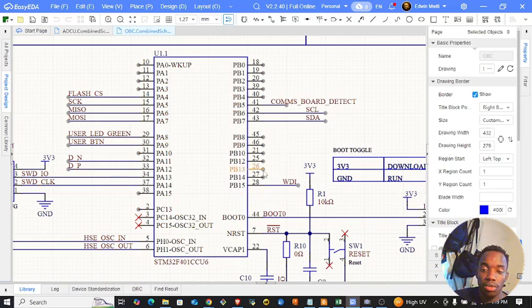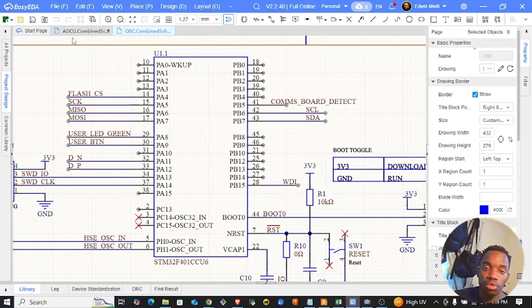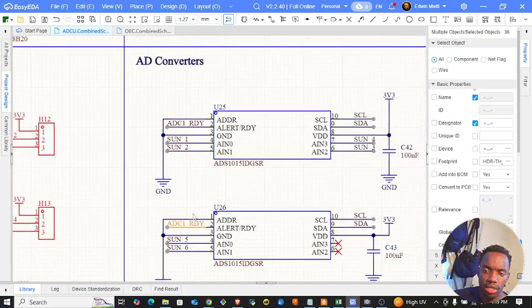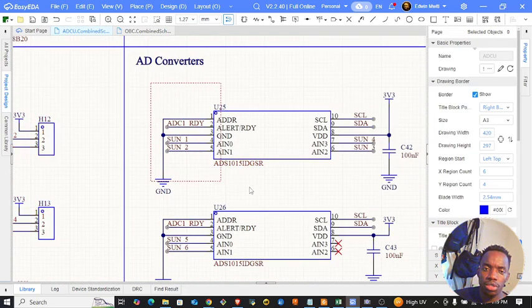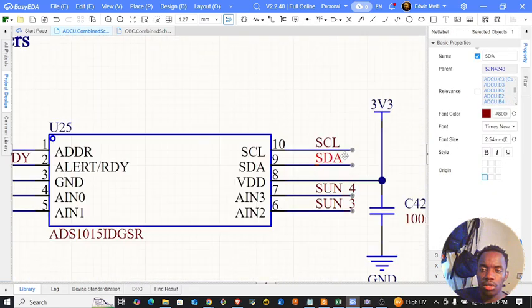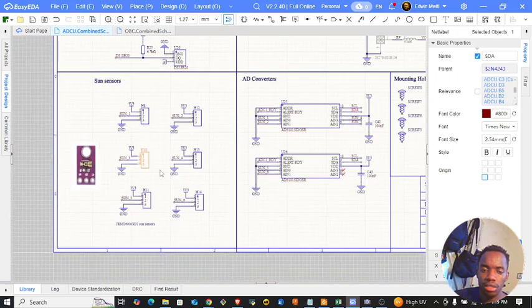And since I'm not done with some of the systems, I don't want to risk giving all those pins to a single point. So what I did, I connected these sun sensors through analog to digital converter chips, external converters that communicate through I2C, right? So by doing this, you have just used 2 lines to connect 6 sensors.